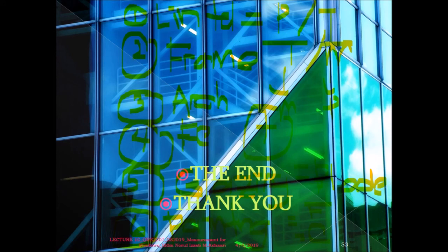Then I would like you to prepare the taking off list for only the type of the window applicable in drawing number 7. If you see that the detail is available in drawing number 9 and 10, but the window is not applicable in the layout plan, then you don't have to measure.